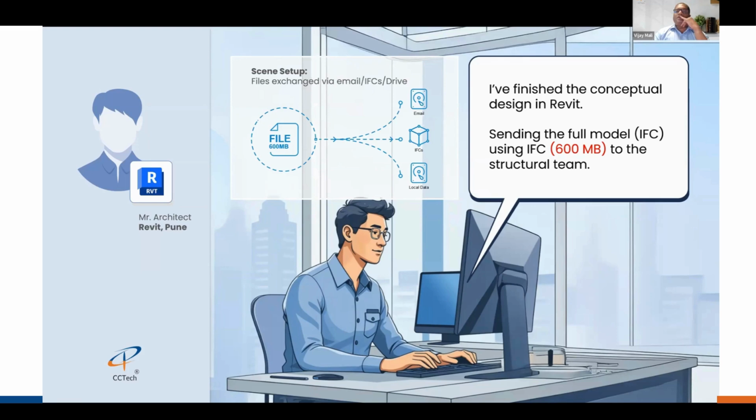He has just finished a conceptual design layout in Revit, and he wants to send it to a downstream detailed design team, which wants to do the structural design. Considering the conceptual level of the design, the file is about 600 MB. He is using IFC as a method to share this data from Revit to a downstream Tekla application.